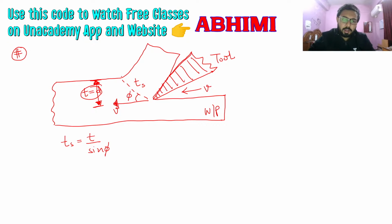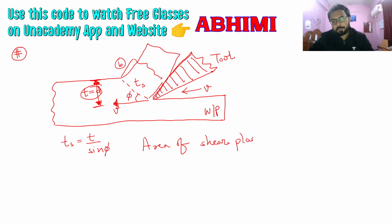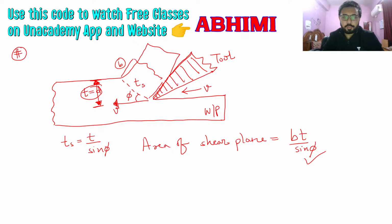So if this is the width of the workpiece, then the area of the shear plane will become b t divided by sine phi. And how it is becoming that, I hope you can clearly see in the figure, and you can just remember that, because this is a revision class, so I expect you to study if you have studied this before. So let's just discuss now about the Merchant circle. Let me show what are the things that are left.